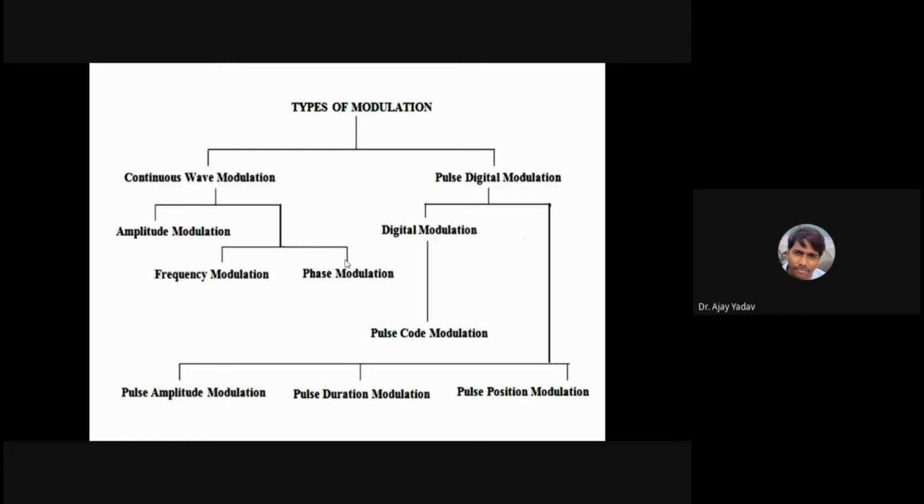Now the other person speaks and sends information towards you, and when that person says over, only then can I start speaking. Both channels exist, both can speak, both can hear, but not simultaneously. So this is called the half duplex type of electronic communication system.